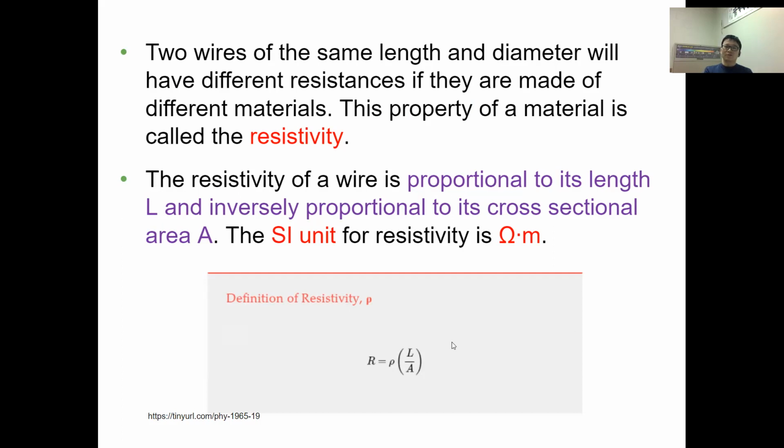We call it rho for resistivity, and resistivity is proportional to resistance, okay? To calculate resistance, that's equal to resistivity times the length of the material divided by the cross-sectional area, okay? So R is proportional to the resistivity, proportional to the length, and inversely proportional to the area.